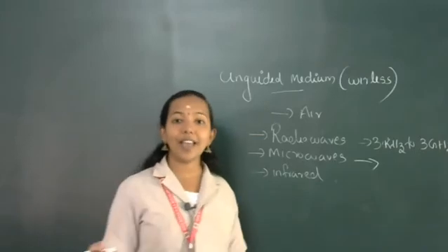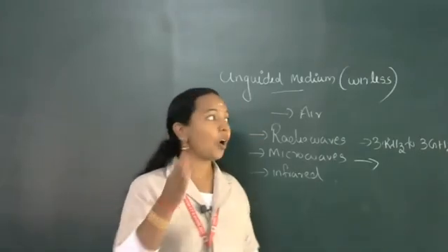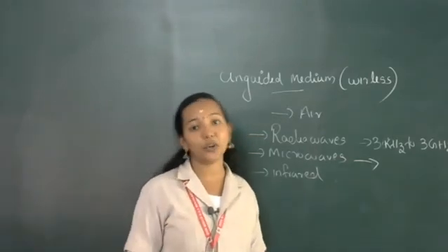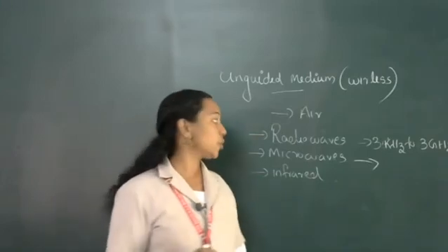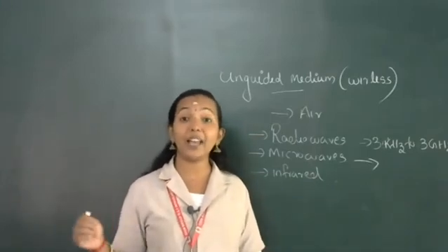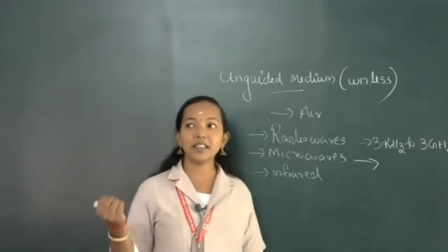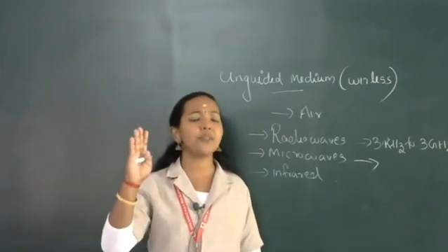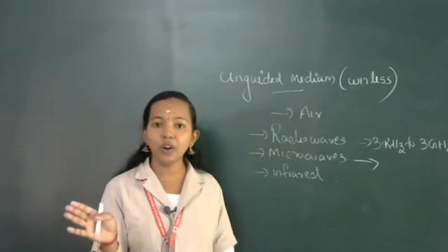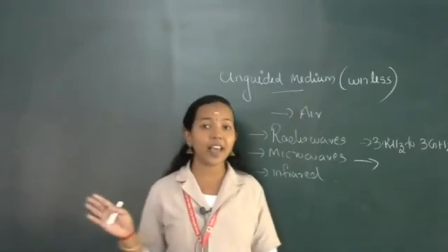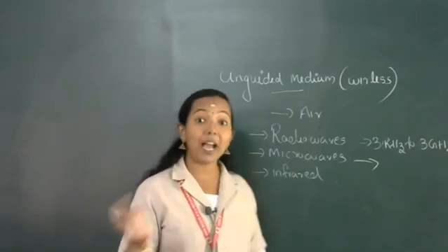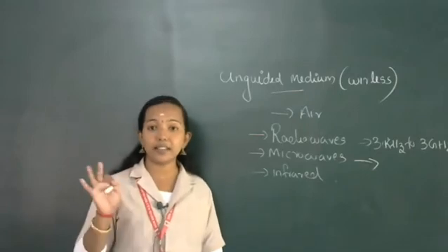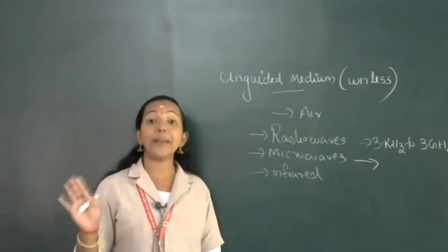If we are placing the antennas on a hilly area, there will be no obstacles between the sender and receiver, because the height is very big. There will be less chance of obstacles between the sender and receiver. So in microwave we are using line of sight data transmission. If any environmental issue affects the antenna, that means the direction of the antenna changes, then there will be no data transmission. If there is any mistake in the direction, we can't transfer the microwave signal, because line of sight is a must and microwaves have no penetrating power.